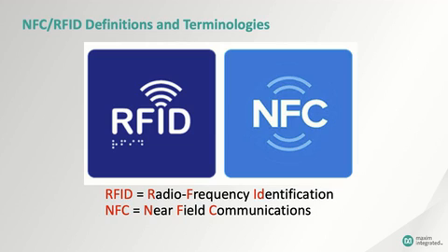NFC stands for Near-Field Communications. Now, NFC is best thought of as a subcategory within the RFID universe. While the broad definition of RFID spans many RF technologies, NFC is defined by very specific standards for operating frequency, types of modulation, emitted power, range, and bitrate. In short, NFC is more focused on secured systems that govern operations like payment and access control, where confidentiality and data protection are essential. The bottom line is this: you can think of NFC as a specialized instance of RFID.